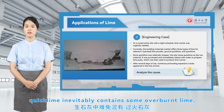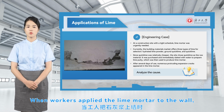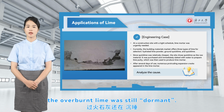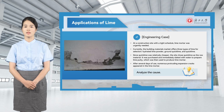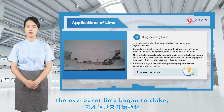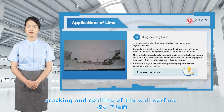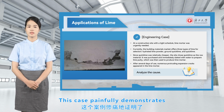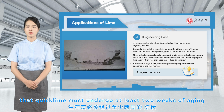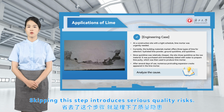As we know, quicklime inevitably contains some overburnt lime, which slakes very slowly. When workers applied the lime mortar to the wall, the overburnt lime was still dormant. By the time the mortar had already hardened and set, the overburnt lime began to slake, causing significant volume expansion and ultimately leading to cracking and spalling of the wall surface. This case painfully demonstrates that quicklime must undergo at least 2 weeks of aging before use. Skipping this step introduces serious quality risks.